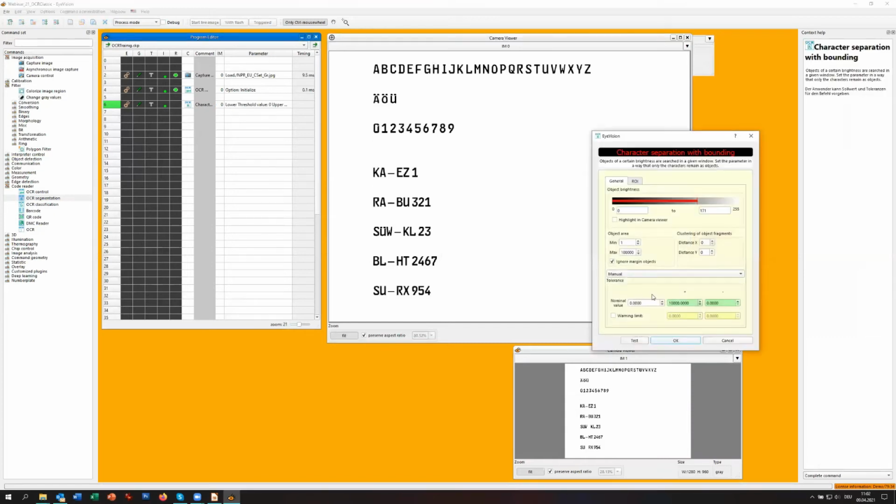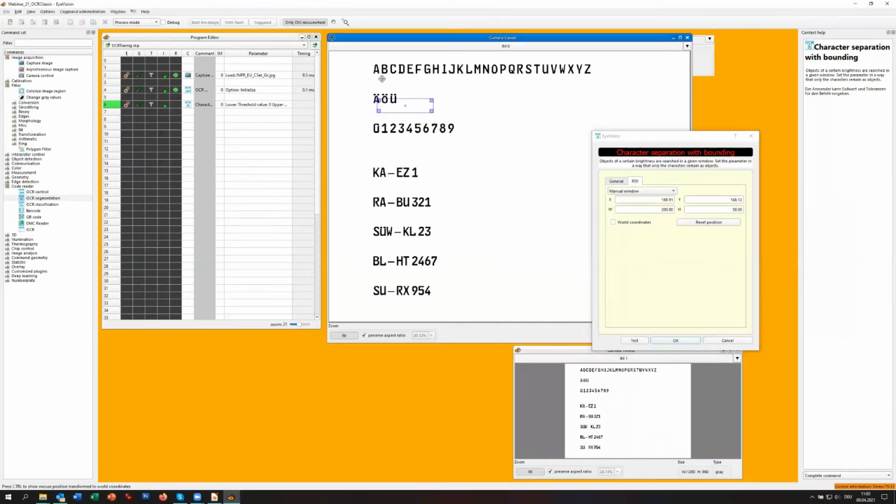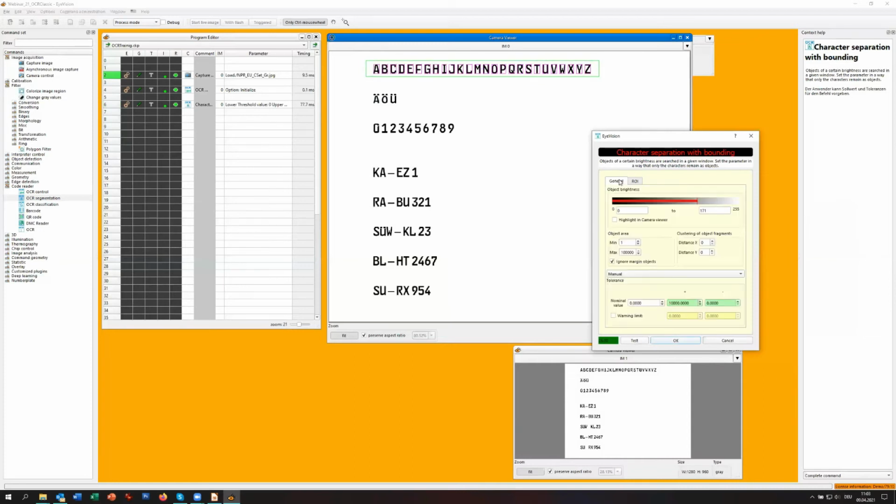But in this case, yes. Anyway, we go to the region of interest and we tell the system, look, here are the characters, our training characters. Of course, if you have never trained the system, you need to train it, and that's what we're doing first here. We train the character set and we say, okay, let's test it. And if you have a very good illumination, you don't have to think so much about it. The standard configuration is good. In this case, we are finished. The segmentation system, in this case it's segmented, can find the characters by itself without doing anything.